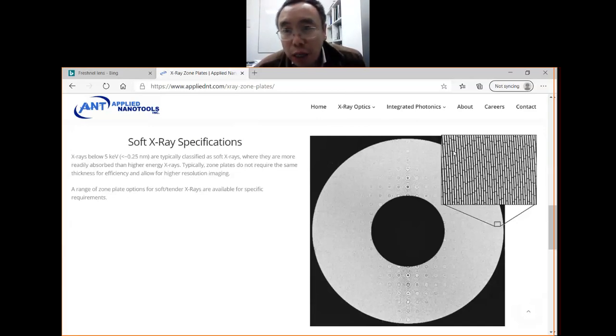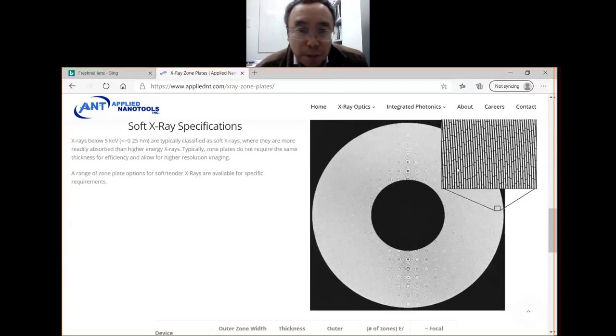Before we do electroplating, we need to make the e-beam resist structures. The black color here should have been electron beam resist like PMMA. But if we have a very thin and tall PMMA polymer structure, it will not be mechanically stable. So we need those black parts to make sure the lines will not fall together, because this black part will support the white resist lines.